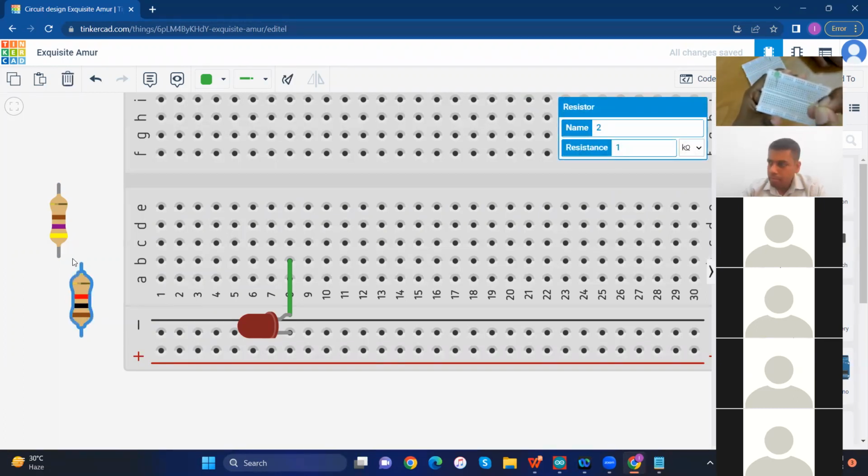Then purple and yellow. Yeah, brown, purple, and yellow. Then it starts from the yellow side: yellow, purple, brown, like that. If you have a 330, then I will show its color code. Then orange, and the next one is brown, like that. Hold it with the gold color band on one side, and then you can read the bands: yellow, purple, and brown in that figure.